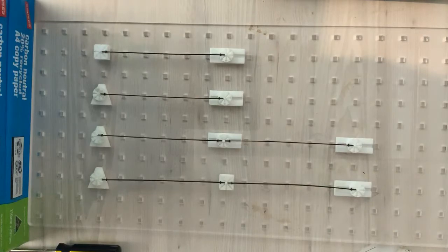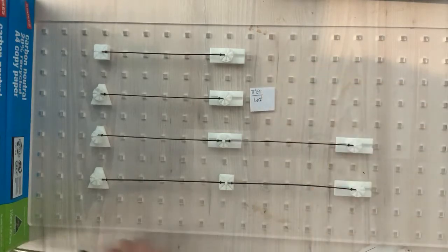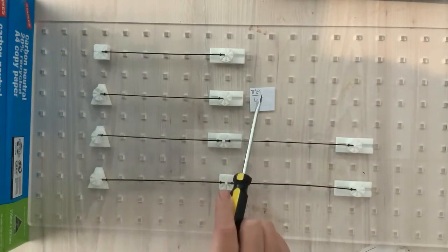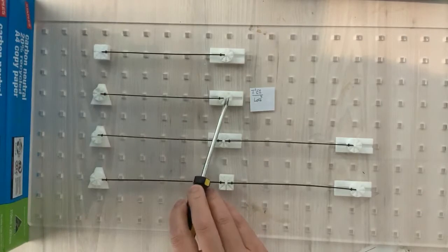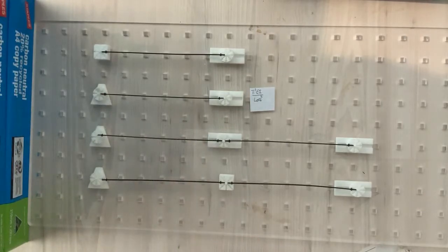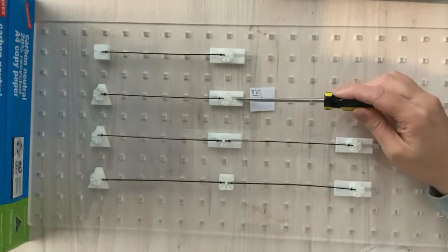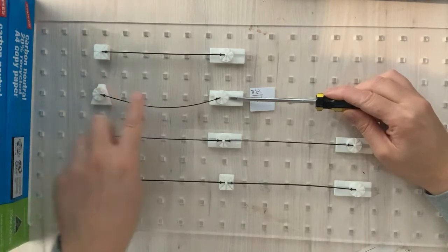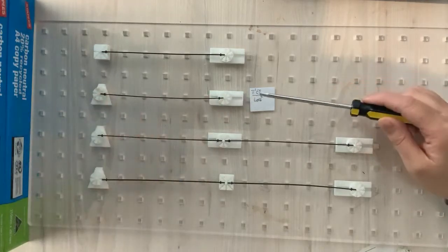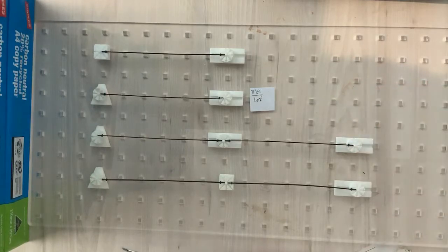One of them is this concept of the effective length. So we would say that this one is pi squared EI over L effective squared, and in this case here the effective length is 1, because the effective length is the actual buckle length, or L effective is the half sine wavelength. So when we apply that, the effective length is the same as the buckled length or the half sine wavelength, and so whether it's L effective squared or L squared, it doesn't make any difference.